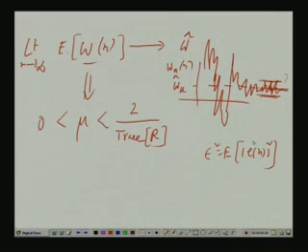But if you do not put the optimal filter, naturally the error is not minimized. What is epsilon mean square? That is, if you really put the optimal filter weights, find out the E n and find out its variance, that is the minimum possible error variance attainable, which we call epsilon mean square.